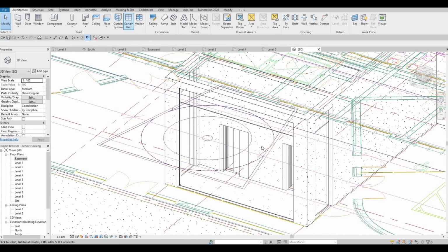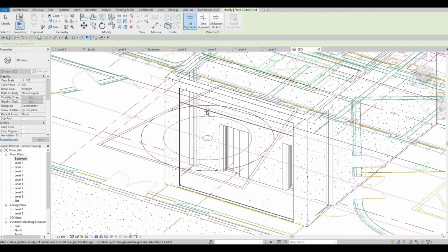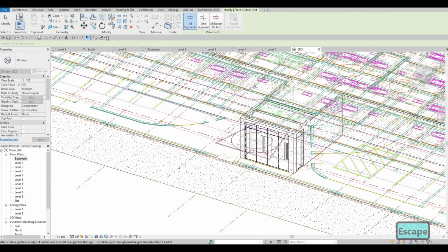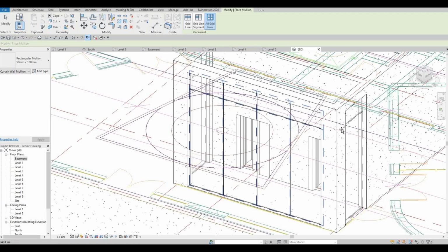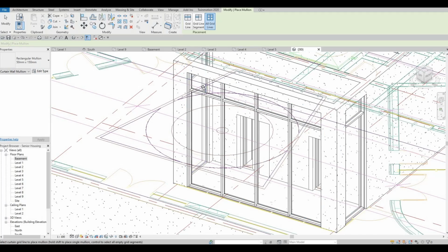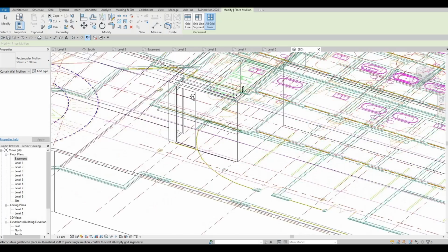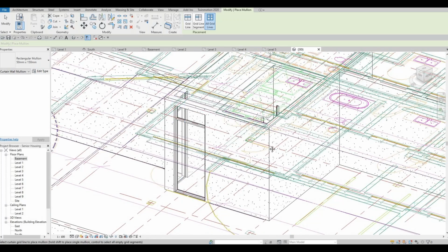And then here I know this is too big, so I'm gonna add a curtain wall, maybe 4 of them. So I just need to go around in the middle, so it will divide it perfectly. So 20 25 70, and then we could go middle again here, and then middle again here. So that's done. After that, go to architecture and add in mullion, all grid. I'm gonna add all grid here, here, and also here. I'm gonna add it here as well.